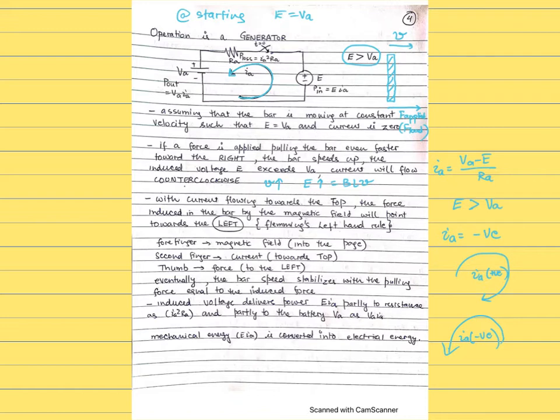The current is leaving the positive side in here, and the current is entering the negative side in here. So this is your source of power now. That's your input power, and the value is, of course, E times IA. That's the source of the power. And this element is consuming, and this element is also consuming. Here it's through the resistor, so heat loss, and here it's actually your output power now.